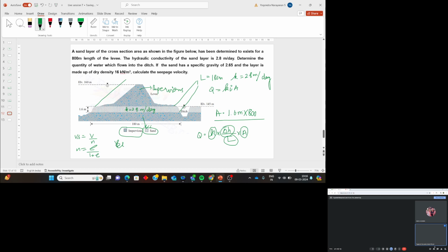Gamma d is equal to G gamma w by 1 plus e. So from this you calculate e. Did you understand? Yes, sir. You can get e now.